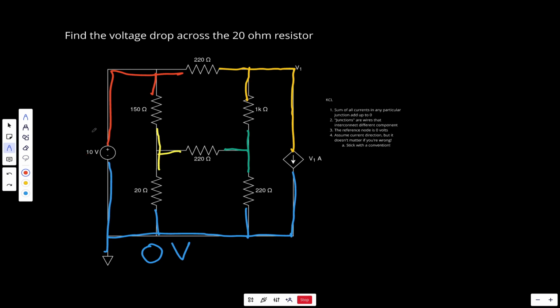So what exactly is the voltage level of this red wire? 10 volts. Now notice the voltage of this red wire is completely different from the voltage of the blue wire, and it may be different with these wires. We just don't know, but most likely it will be. Just act like these wires are all separate voltages, and that's pretty safe to assume.